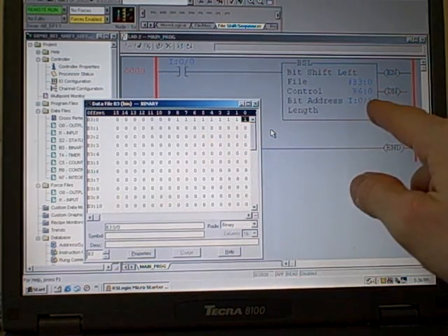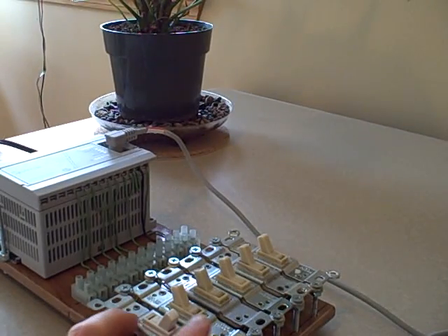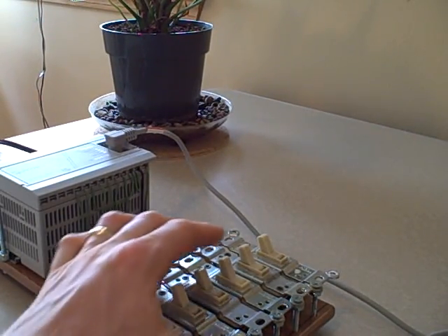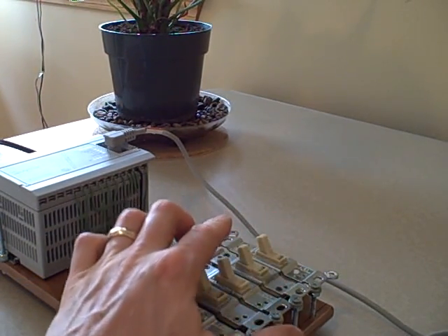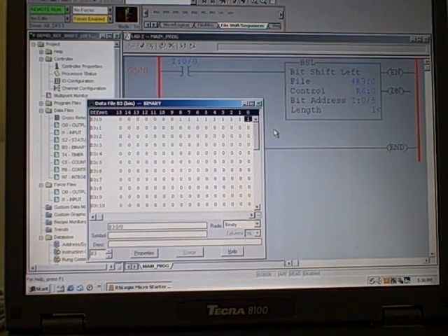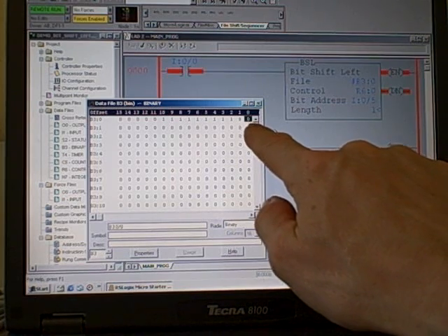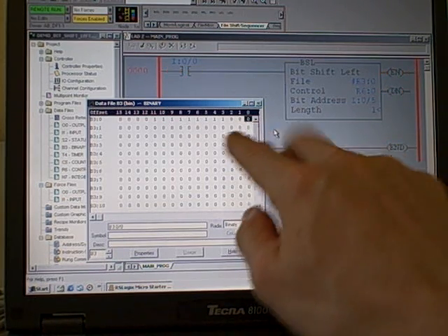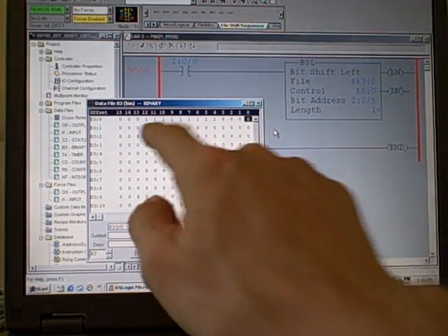Now, if I take the 5th input switch and turn it off, I'll go back over here and show you. Take this one and turn it off. Now when I begin to move input switch number 0 and cause the shift register to move to the left, we'll see 0s being entered into that word from the right-hand side. So here we go. Let's watch. There's a new 0. There's another 0. There's another 0. Notice all the 1s marching over. It's a shift register shifting all these over.